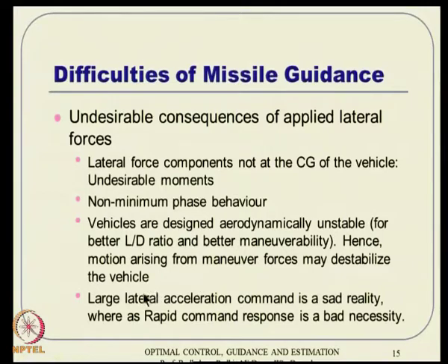And also remember that large lateral acceleration command is a sad reality. That means, the targets are becoming more and more powerful, they have more and more maneuvering capability. So, we do not have the luxury anymore not to have large lateral acceleration commands. These modern day missiles, especially these defensive tactical missiles, have to have large lateral acceleration.